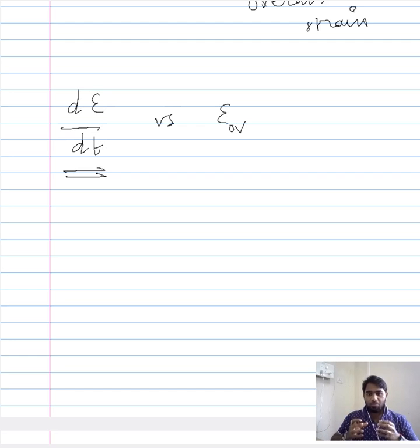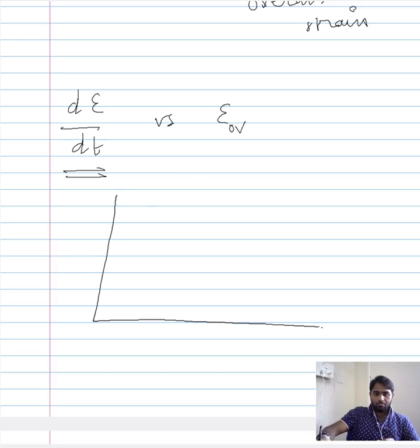Now, when you plot it without any prior experience or prior knowledge about the creep curve, you plot the time taken for a particular strain against the overall strain. You are considering the overall strain and plotting the time taken for a definite section of the strain, and ultimately what you are plotting is the change in the creep strain rate, because you are studying the condition of creep.